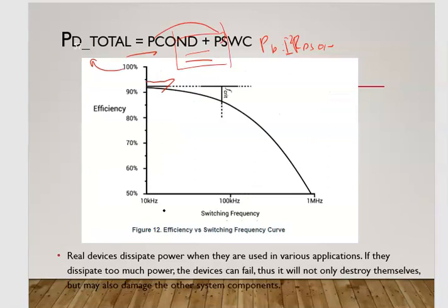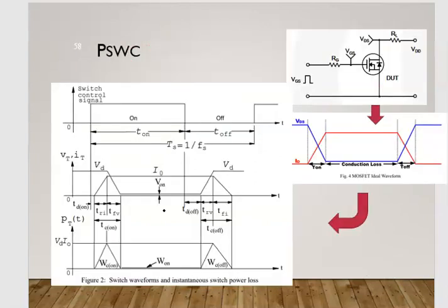So we shall see that when we switch the circuit, this is the transistor V drop, voltage drop, during switch on. During the switching itself, there is a response whereby the increment of current takes place and the dropping of V across your drain to source is dropping, and the response is some sort of delay here.